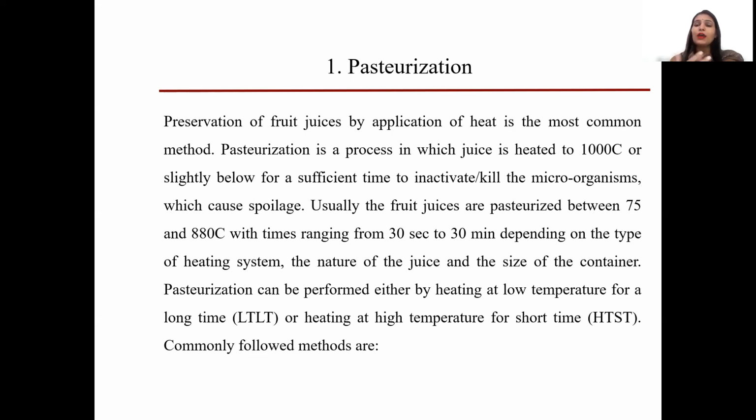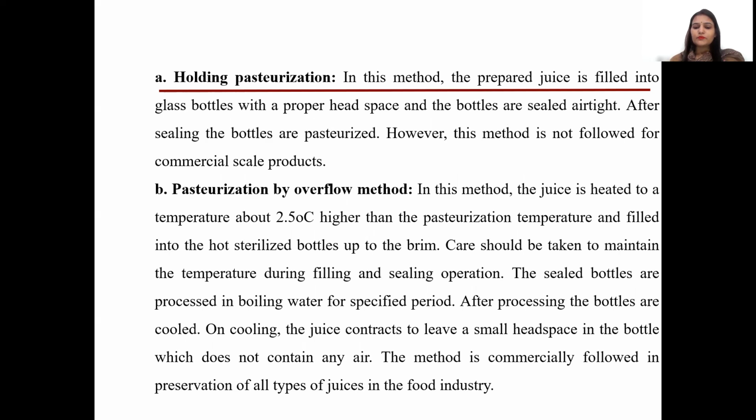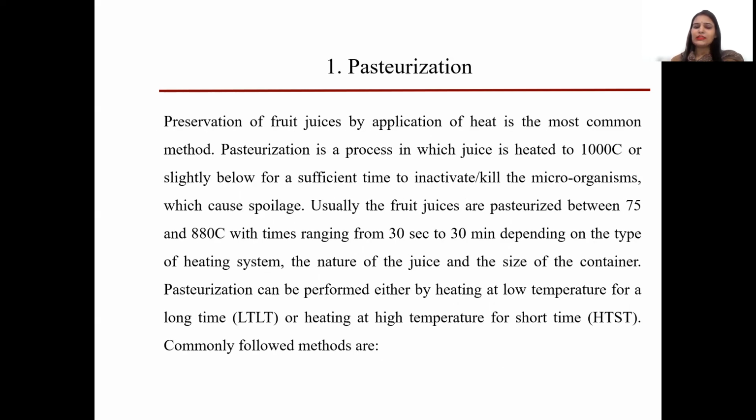If you have a heat sensitive liquid product, we can use HTST: we treat our product at high temperature for a short time, so that specific nutrients, like pigments and antioxidant properties, remain. So we can preserve our food with these pasteurization methods for a long time.